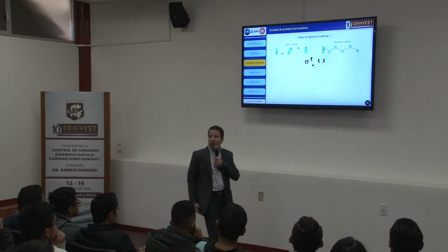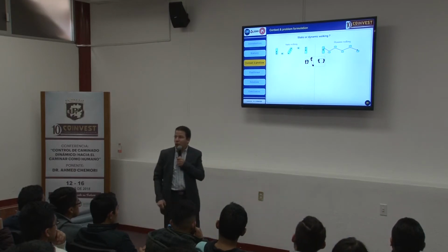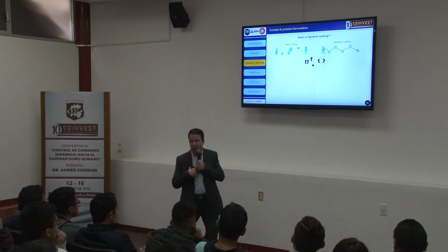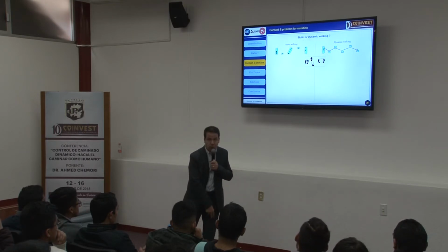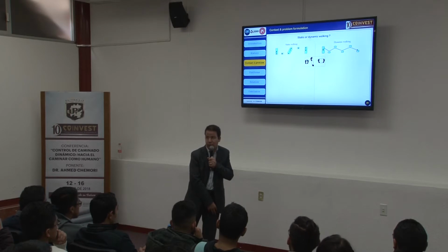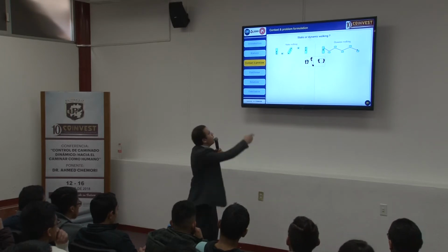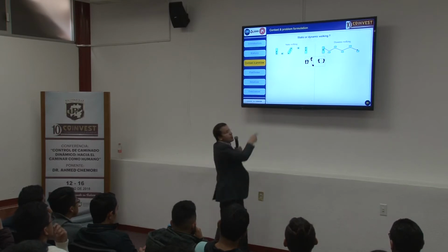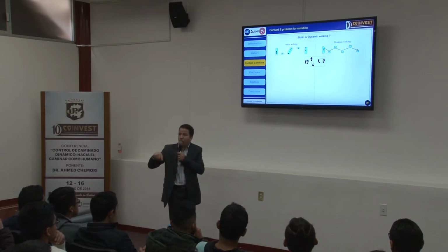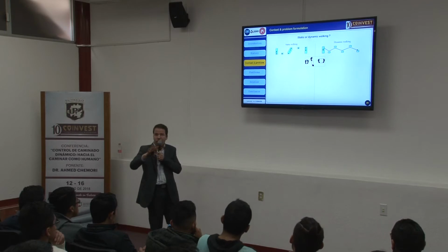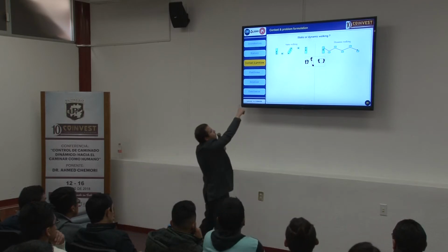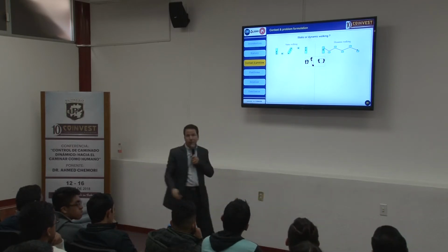If you want to do a step, what do you have to do? You have to move a part of the mass of the body in this direction, such that the projection will be only on this first leg, this first foot, and then you can move, and you will be stable because the projection will stay inside the polygon of support of just one leg in contact with the ground. Then you have to move to the other leg and repeat the same motion.